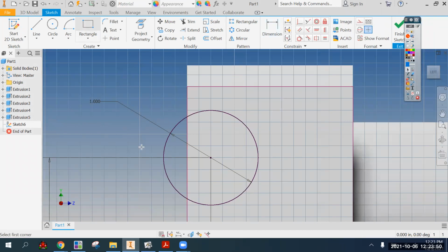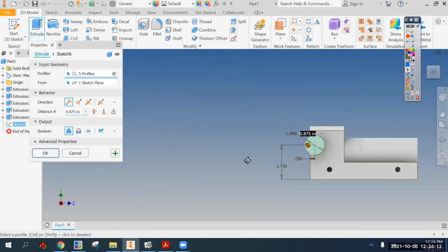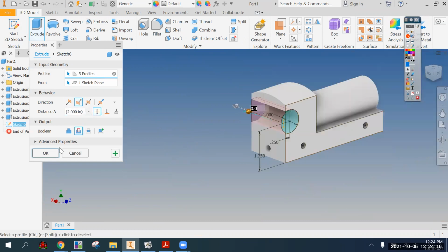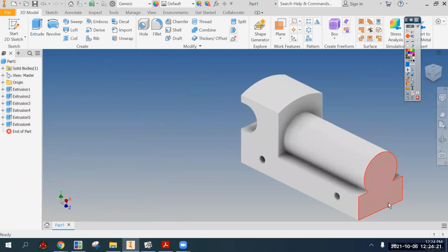I need to make a shape that will cut this off. So I'm just going to get a rectangle, find the top center of my circle and go down, snap it to the back edge, but flush with the bottom of the circle. So the rectangle will now include that. I'm going to finish sketch, extrude, choose the circles and the rectangles and the little bits there, and switch it to cut and cut through all. And there is that. Okay, 2 other features: the 3 holes in the front and probably the trickiest part, the hole for the smokestack on the top.